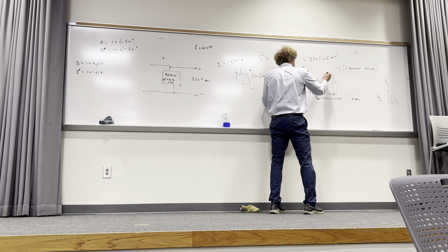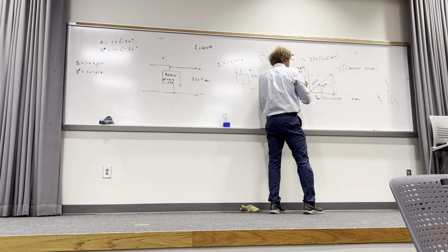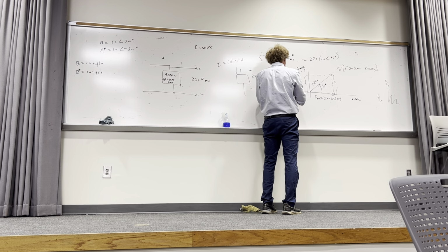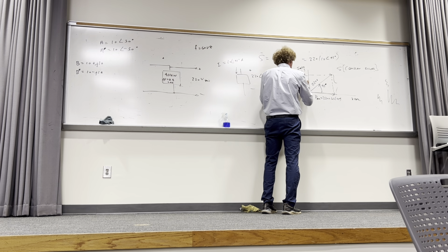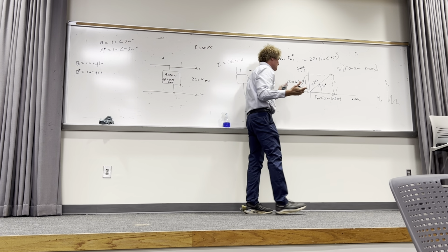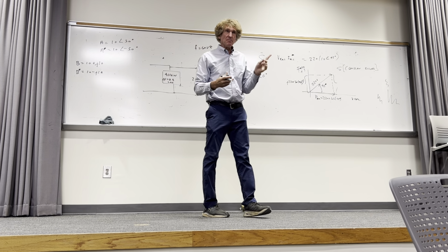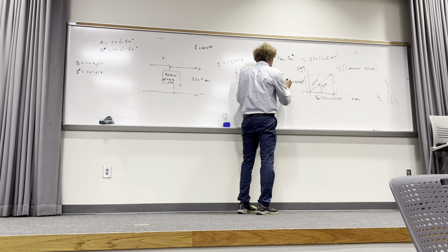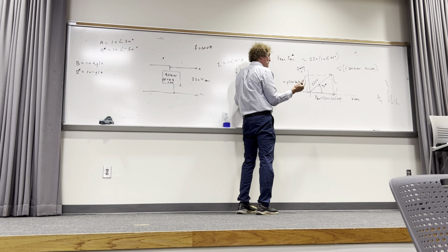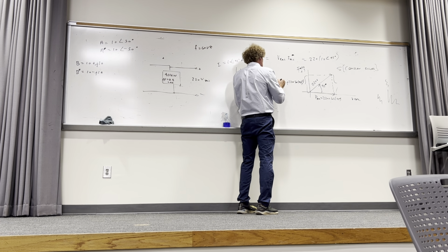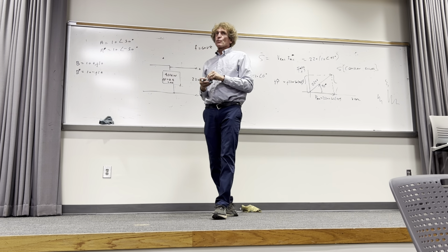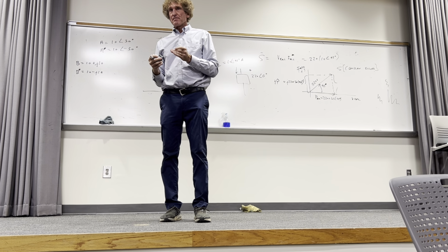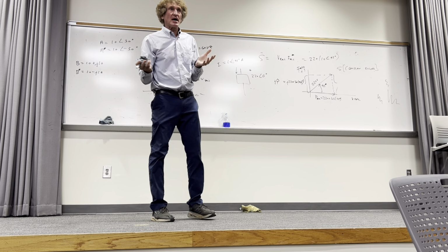So on this axis over here, we're going to have a value of J times 2,200 times the sine of 45 degrees. At 45 degrees, sine and cosine are the same. You all follow me? The symbol for this, by the way, consistent with the book, is Q. This is actually JQ. Now Q is just a symbol for reactive power. You all with me? It's just a symbol. Doesn't mean much other than that.